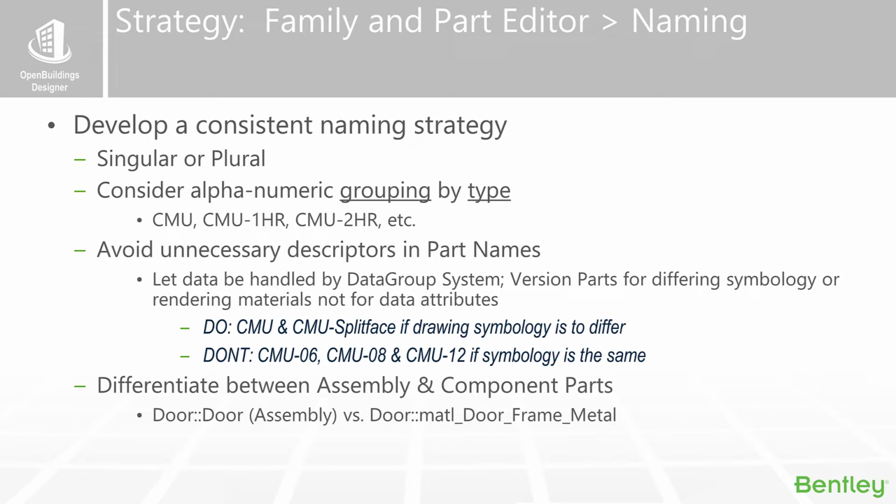You might want to be grouping them by CMU, CMU 1 hour, etc. We don't want to have too many descriptors in the part names themselves. So you do want to have like CMU, CMU split face, but as I mentioned before, we don't really want to be putting the actual size of the CMU itself into the actual name of it.